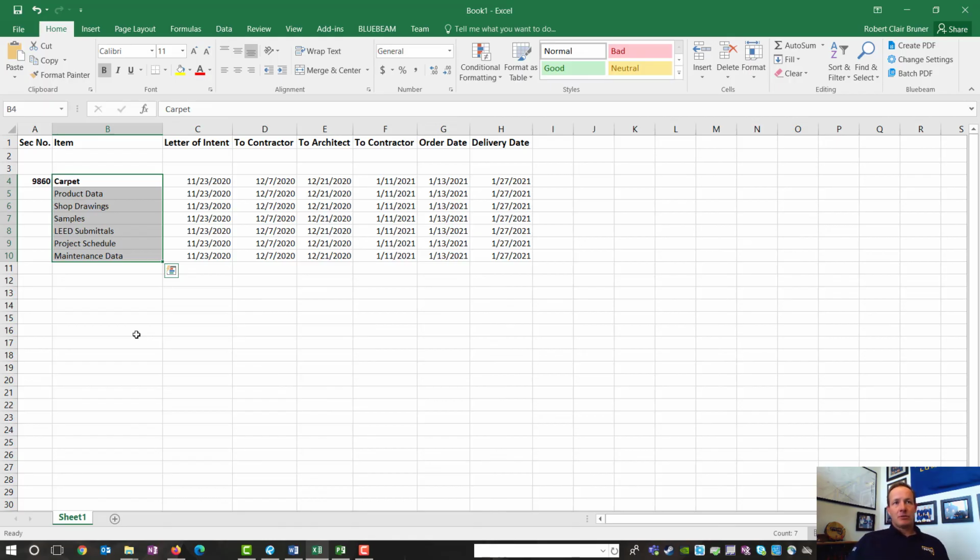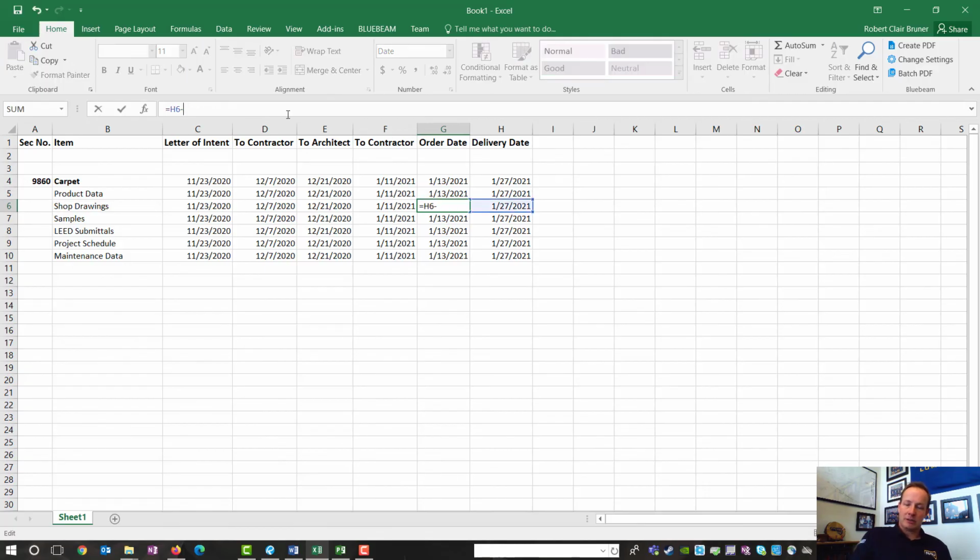And I'm less concerned with the durations on your schedule, because this is not a scheduling class, as I am with you paying attention to, okay, there are different lead times. So let's say there was a different lead time for the shop drawings here. I'm going to give the shop drawings 28 days. Okay, all of a sudden that pushes that back to 11/9. So really all these need to be in by 11/9 because it's the same subcontractor.